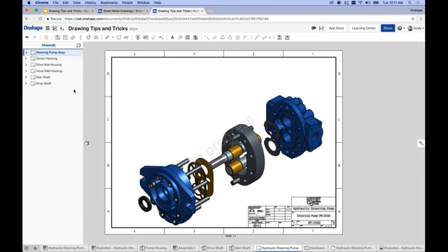Now, keep in mind the selections are just like selections in a sketch. It's constant. So if I select multiple sheets, I'm dragging multiple. But I can easily drag one down and reorder it, or drag it back up and reorder it. I can also right-click, move up, move down. Right, that's another option, as well as rename, delete, go to the sheet properties of an individual sheet. All of those things are available when I right-click on a sheet in the Sheets flyout. Another question, of course, how do I create a new sheet? You'll see the Insert Sheet icon here, right?